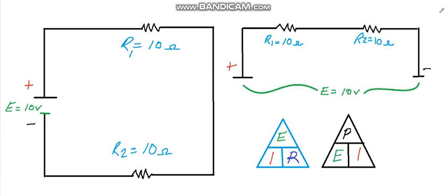Okay, introduction to series circuits. I've drawn a series circuit, the same series circuit two ways, to illustrate something here. Series circuits are often called linear networks. And all that linear means is that there's essentially one path for current to flow. So the current flows up like this and then back to source.